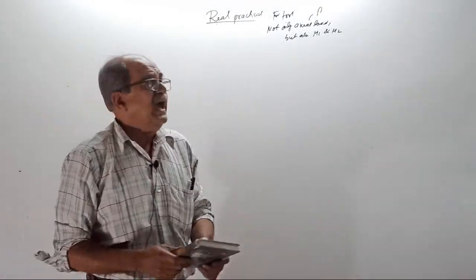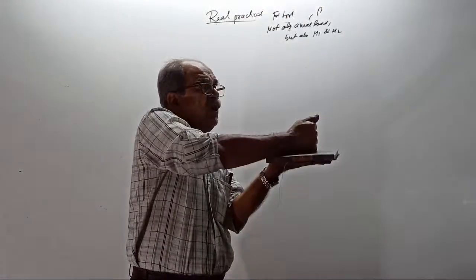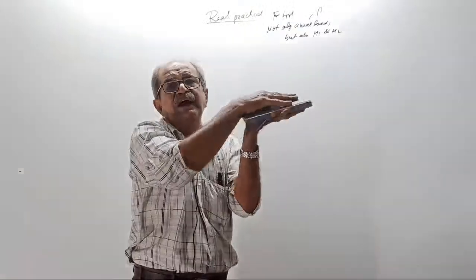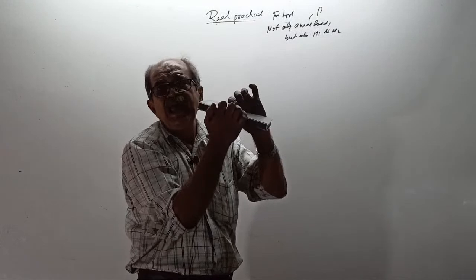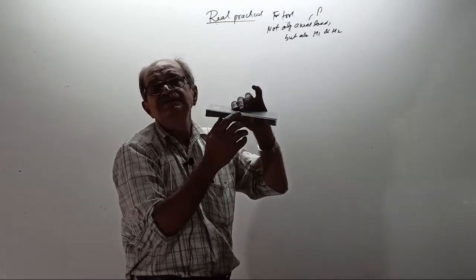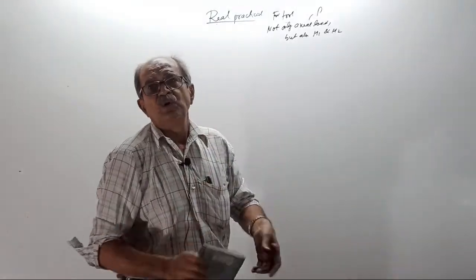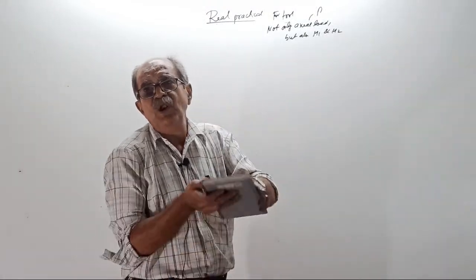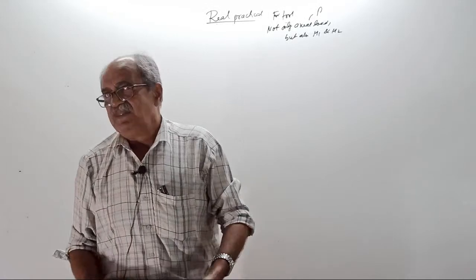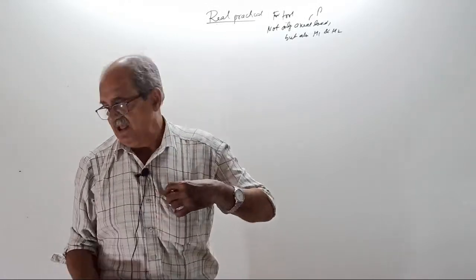Clear? Therefore, axial load will give you uniform pressure. Bending, this M1, M2 will again give varying pressure because of the bending equation. So resultant pressure will vary everywhere below the footing. Clear now? These all you should write. I am dictating. What all I told you should write.